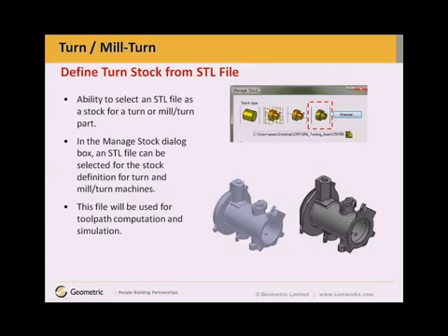As you can see from the image of Stock Manager in turn or mill turn mode, there is a new option which will allow you to select an STL file as stock. This STL file will be used for toolpath computation and for simulation. So let's see this with the help of an example file.